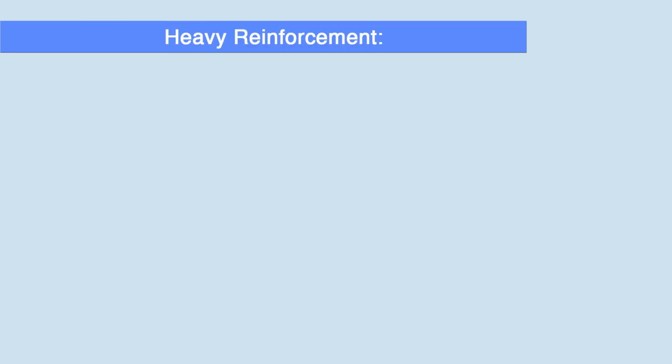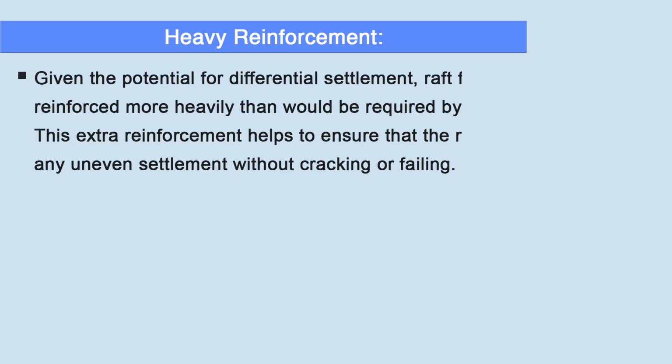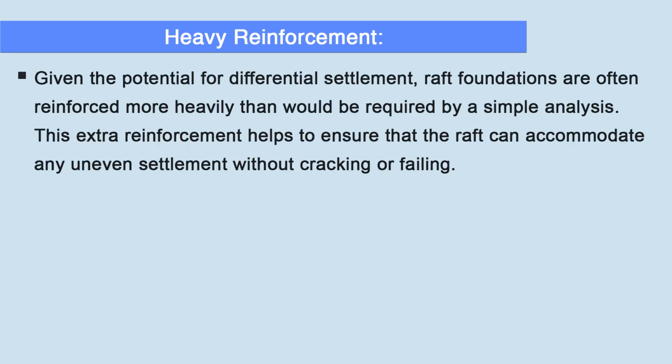Then the next is heavy reinforcement. Given the potential for differential settlement, raft foundations are often reinforced more heavily than would be required by a simple analysis. This extra reinforcement helps to ensure that the raft can accommodate any uneven settlement without cracking or failing.